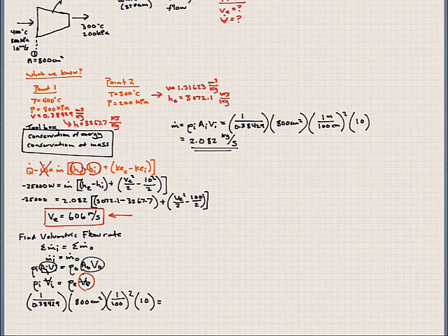All of this is equal to the density at the exit, which is 1 over the specific volume, 1.31623, times the volumetric flow rate, which we are trying to find.